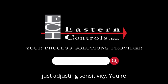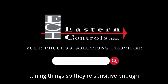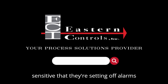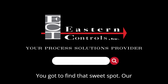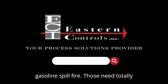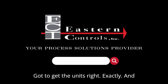So you're not just adjusting sensitivity, you're basically teaching each detector what to look for. Yeah, exactly. It's about fine-tuning things so they're sensitive enough to catch those small fires before they get out of hand, but also not so sensitive that they're setting off alarms for every little thing. Right. You've got to find that sweet spot. Our source gave an example, like a 32-inch natural gas flame versus a massive gasoline spill fire. Those need totally different settings to be detected properly. It's like calibrating a scale, got to get the units right.